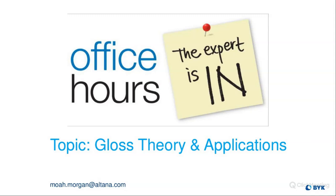Yeah. And so if you were to take something like a gloss instrument and measure a surface that just came out of an oven, that heat is going to affect the electronics internally, and therefore it's going to throw some of your data off. So it's really recommended to not place an instrument of any kind on a very hot surface.